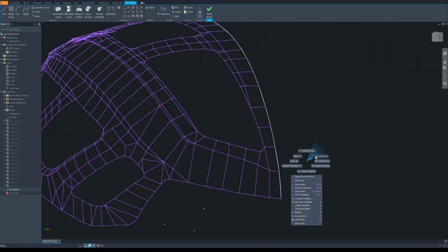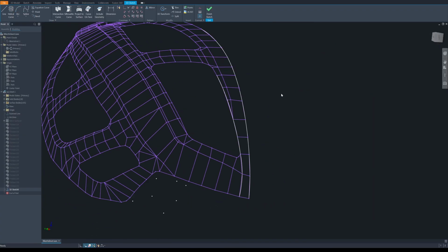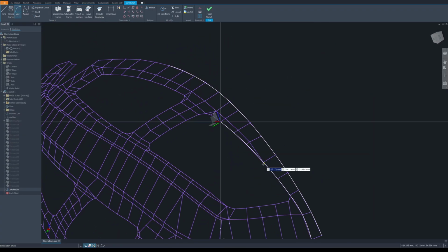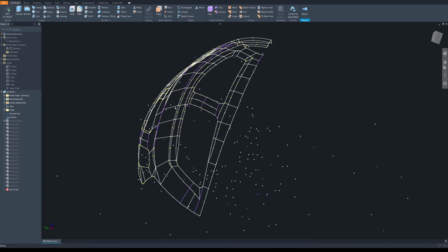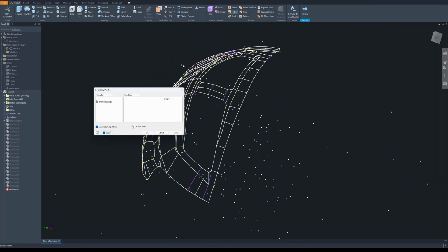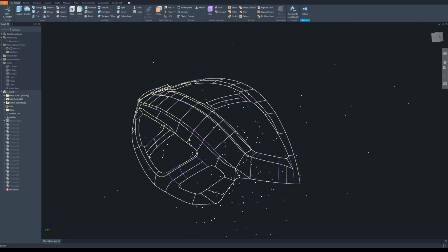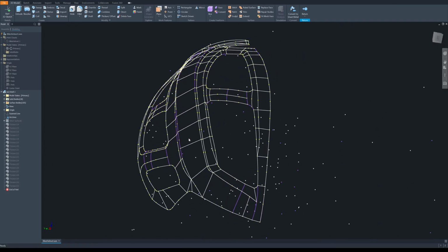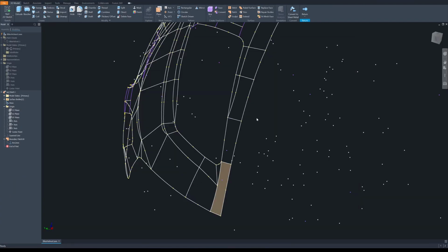See here, and then I make a arc line. Just keep drawing the arc lines like so. See here, it's very easy. It doesn't take long time for this helmet. You probably can do this in half an hour. See my complete arc line that I create with the patch command. I think most of the 3D CAD software has this function. It's a patch command. You can create any kind of surface inside of your CAD software. The only thing that you need is the 3D line. So I just keep on doing this.